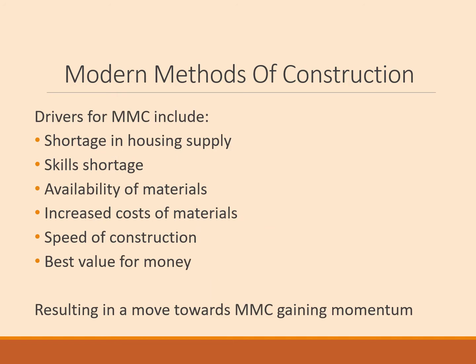In Mayo, and I'm sure a number of other counties, construction heretofore has predominantly been traditional in form, that is, concrete block, external plaster finish, solid timber floor joists, and a cut roof. Use of other construction methods such as ICF has up to now largely been confined to one-off housing.